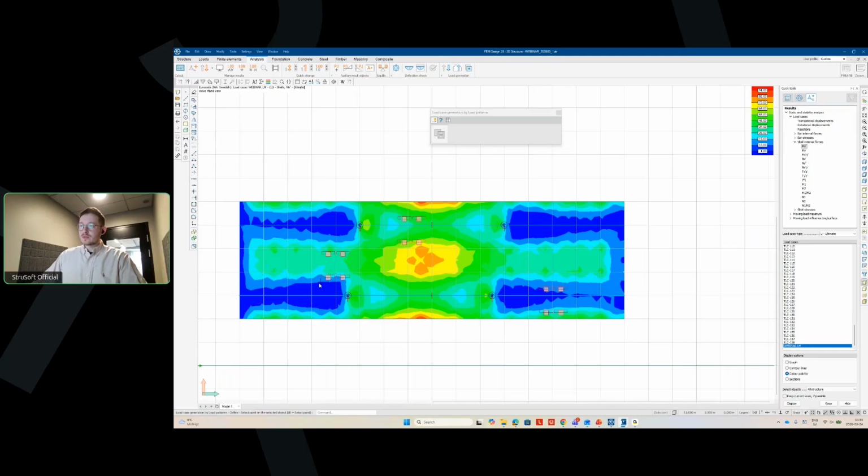And here you can see similarly, it will optimize the positions based on the node that you are currently hovering. Another function here that is nice to use is that you can click on your structure, and then it will generate the load case that it is currently showing you. So this allows you to take this to a load combination, for example, where you can do a nonlinear calculation. Yeah, but that's it for the first example. Let's jump into the next one.